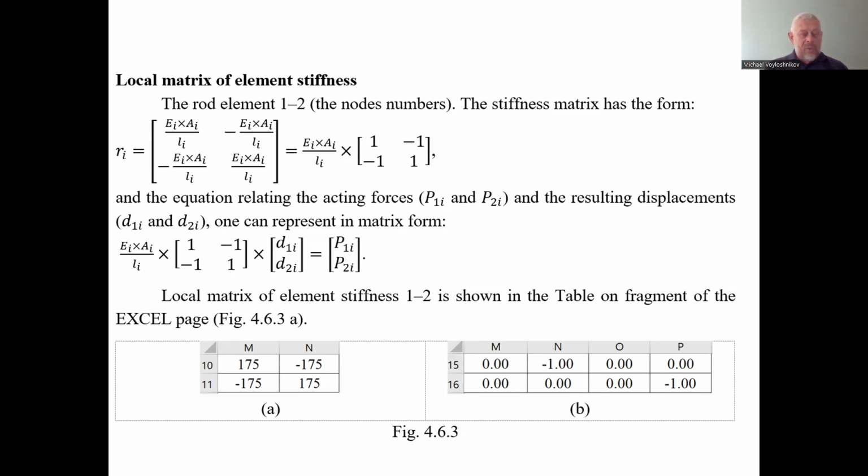Of the two components of forces, we have only the longitudinal component in the local coordinate system and the transverse component. That is why we have the stiffness matrix in the local coordinate system for the hingedly connected number 4 type rod finite element. We have only the standard form of the stiffness matrix of 2 by 2 elements.